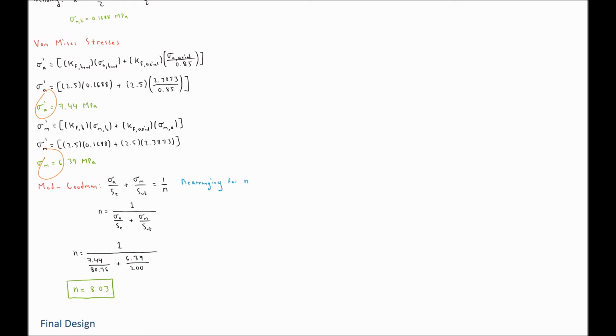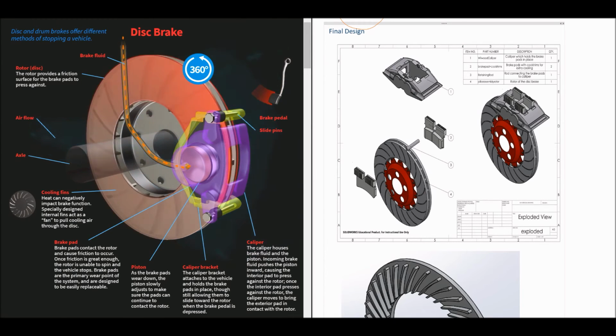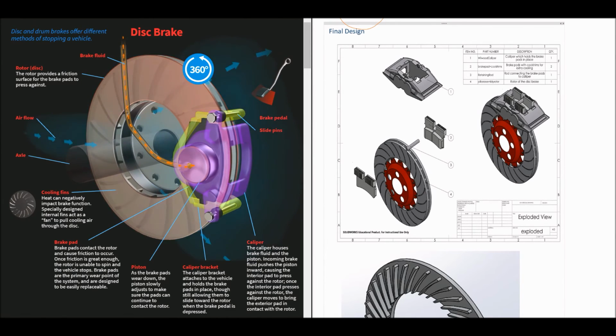Moreover, with this project, we achieved a safe, durable and viable design for the rotor component in a disc brake, taking into consideration the forces exerted by all the components in the brake system. We demonstrated a factor of safety of 8.6 for static loading, which tells us that our design is relatively safe and will continue to function and not fracture. So we conclude that our design is safe because the factor of safety is greater than 1 and the expected lifetime is more than 600,000 cycles before replacement.